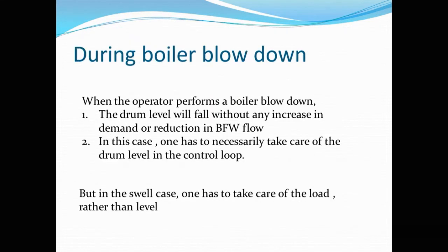There is another situation where three element control is very effective. That is when you are blowing down the boiler. At predetermined frequencies, you have to blow down the boiler to maintain the solids at a predefined level. When the operator does a blowdown, the level in the drum will come down, but the steam production will remain the same.